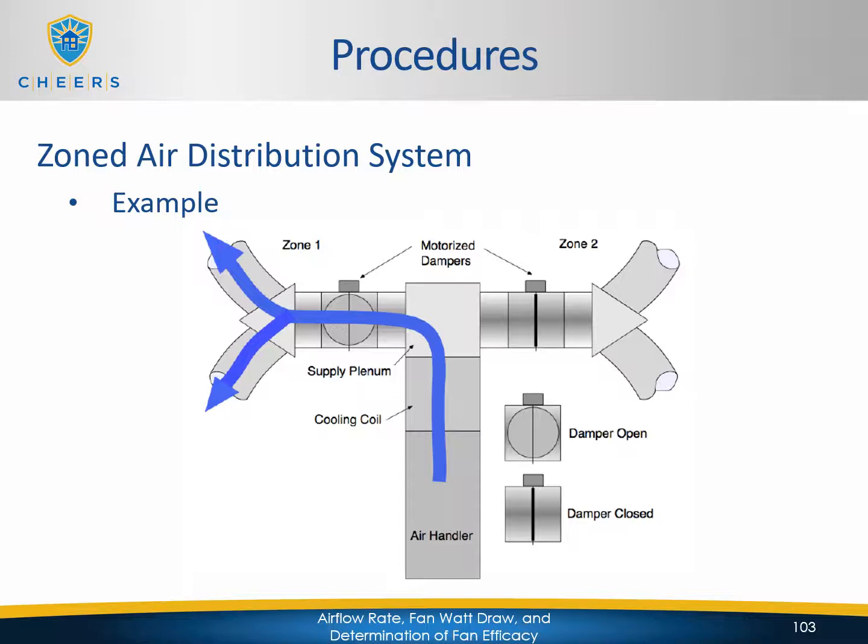So when we talked about the only way to test single speed compressors is to have all zones calling, you basically want to have all the thermostats on to cooling. Therefore, all the dampers will be open and the system will be servicing the whole house at once.